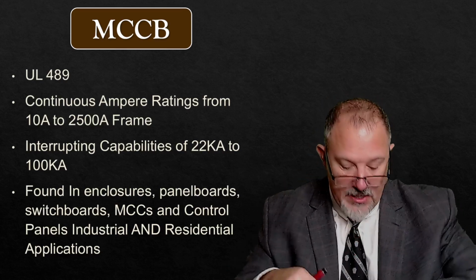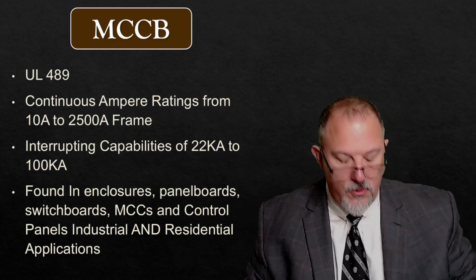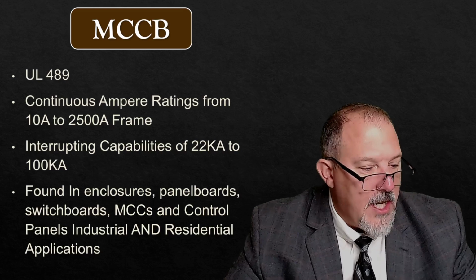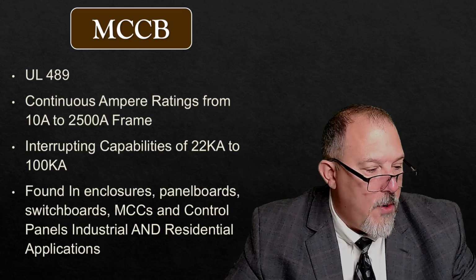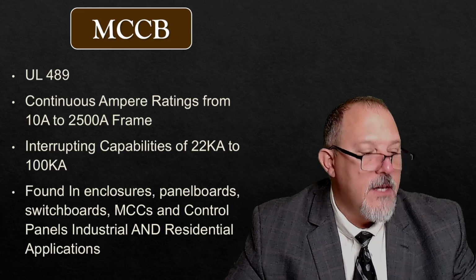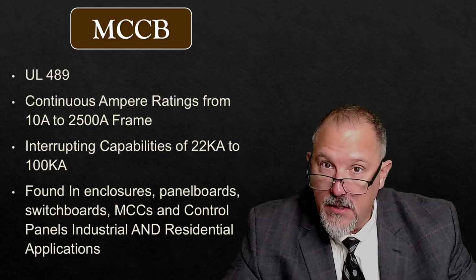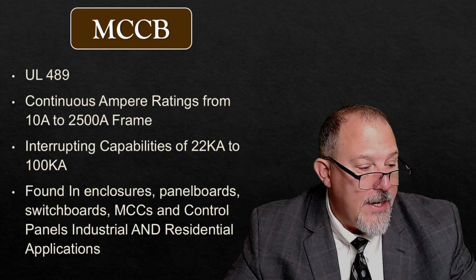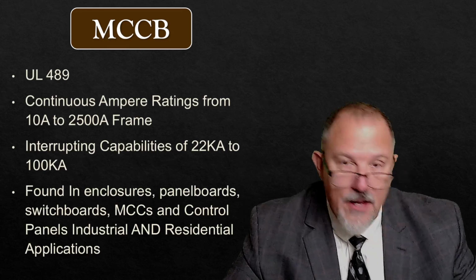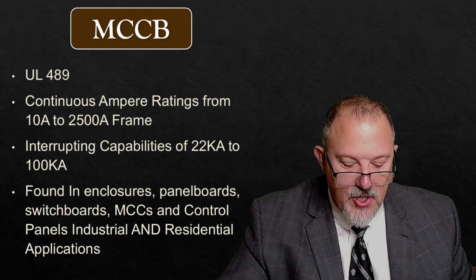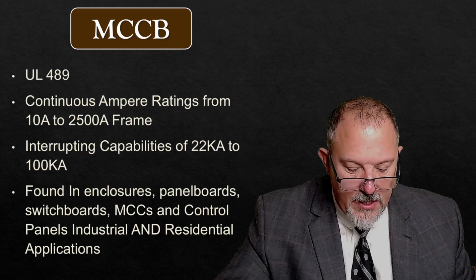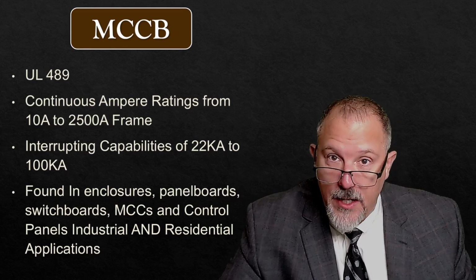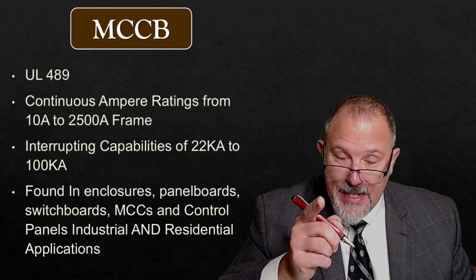That's an important piece. And if you look at the informational notes to this table, it'll tell you that molded case circuit breakers will typically have a 1.5 cycle clearing time. And that's going to be in the instantaneous region. Now, if I look down through everywhere where it says 2 cycles, it says 2 cycles for the first row, panelboards, being fed from a 2-cycle device, molded case circuit breaker.